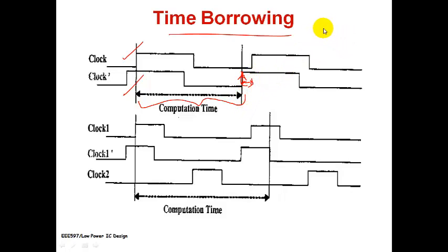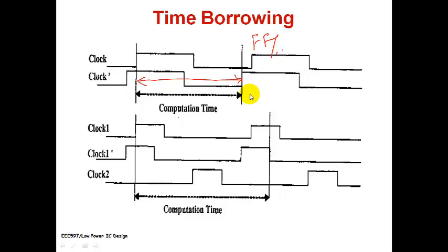So whatever be the frequency at which I had been expecting my circuit to operate, if the logic is going to be taking more time, then the logic cannot be functionally correct, and then I will have to rework on the logic and the frequency. This is what I will have to do if I go for flip-flop based design.